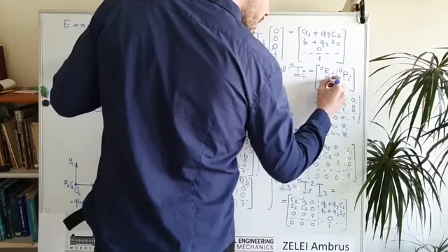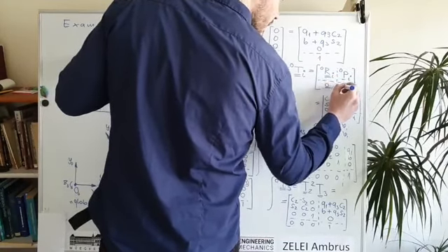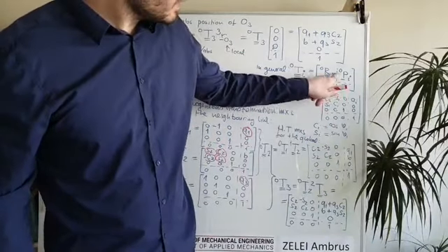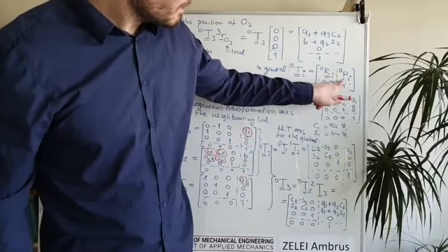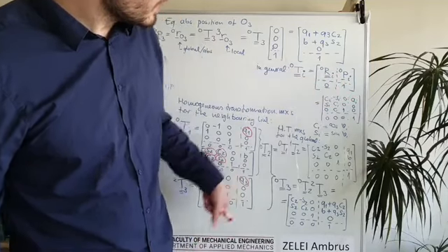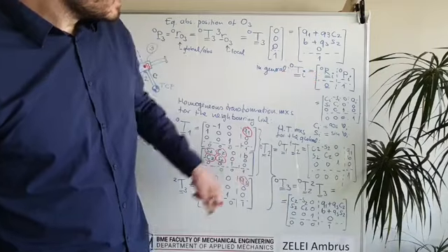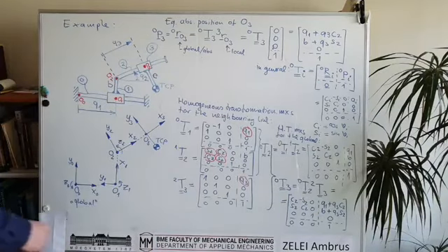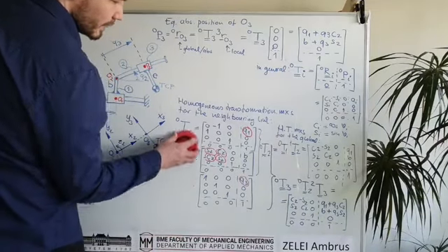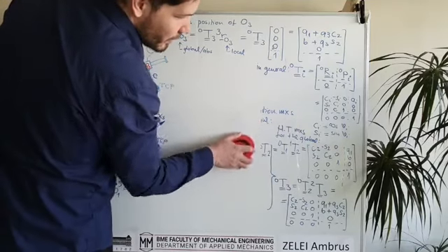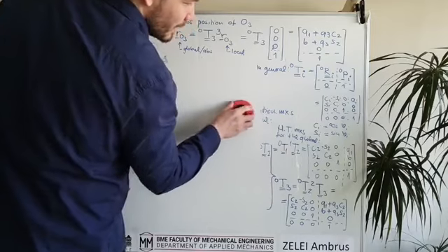And this is very important to know, that the homogeneous transformation matrix basically consists of the position and the orientation of the same coordinate system, and it is given in the zeroth frame. Okay, and another example of the application of these homogeneous transformation matrices